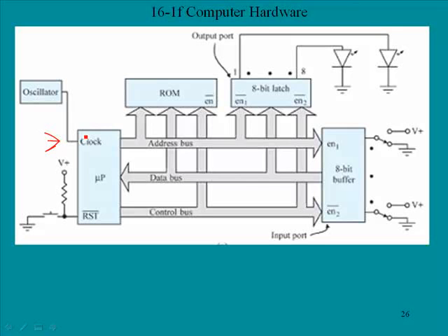Finally, we have the reset input, and this is the reset right down here. We shall assume that our representative microprocessor goes to 000H, and that's for hex, when the reset pin is pulled low. This is to say, when we activate reset, we will force the program counter to 000H, and then it's just going to begin to execute the commands that start at 000H.